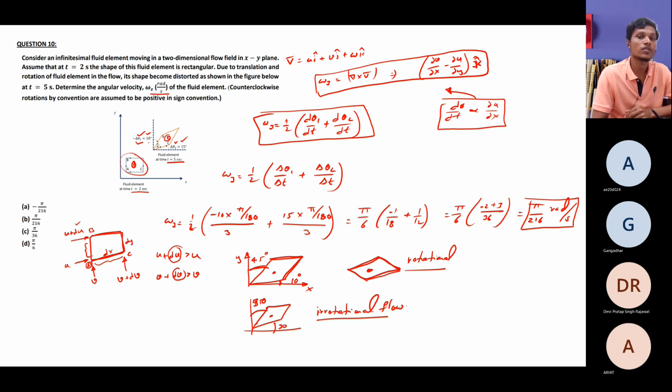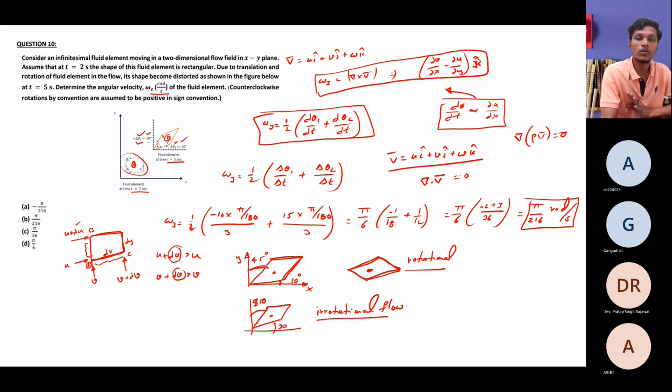No, no, there are no assumptions. If you have any velocity vector, first you need to check whether that velocity vector is possible or not by using your continuity. Suppose my velocity vector is V equals u i cap plus v j cap plus w k cap. The initial thing I need to check is the real existence of this velocity field by using the del dot V bar, the actual continuity equation. If you have the density field, del dot rho V bar, this is a kind of compressibility equation, or you can also call it the continuity equation.